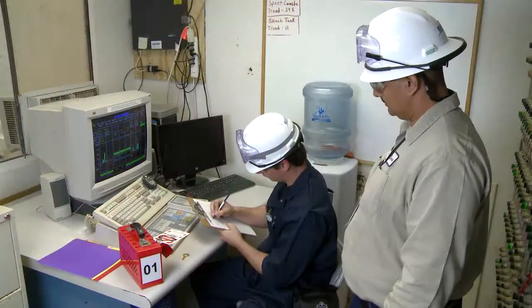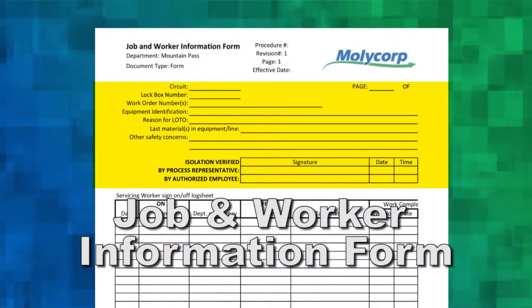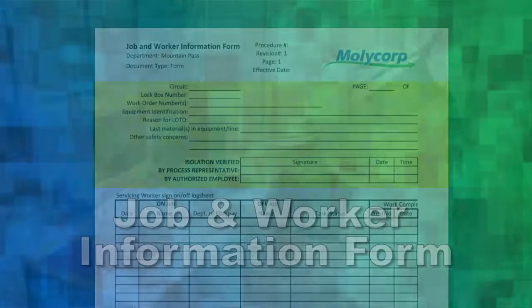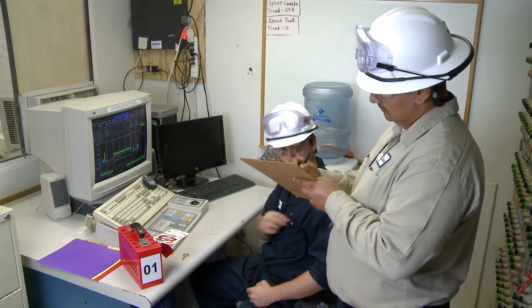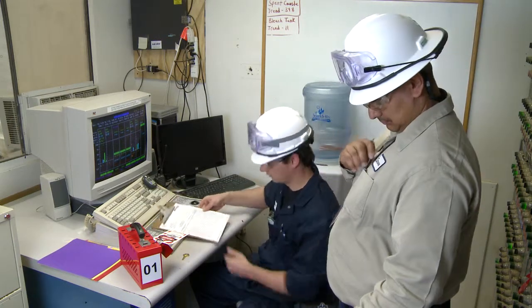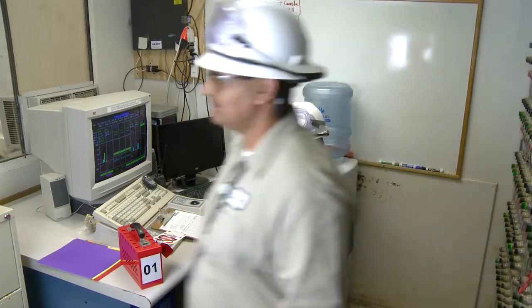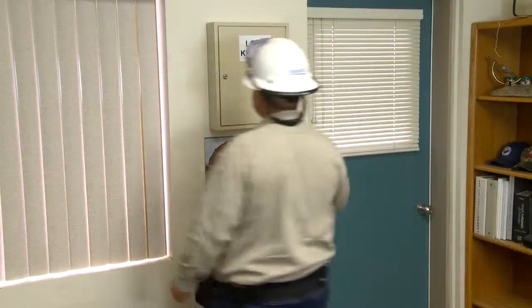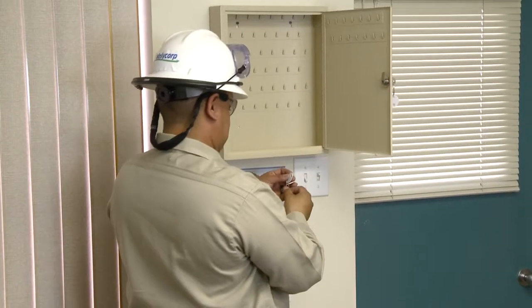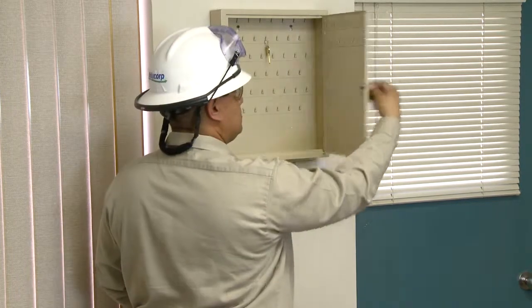The top section of the Job and Worker Information Form must be filled out and signed at this time by the process representative and the authorized employee. The process representative's key to the lockout box is given to the authorized employee. The authorized employee places the key into the LOTO key box located in the shift supervisor's office and locks the key box, retaining responsibility for the key.